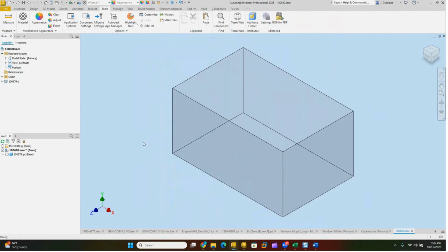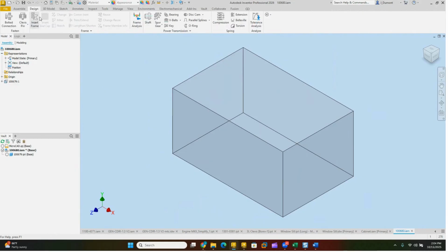names, because if you do the bolted connection, the first time Mike used it or Scott, you're going to create bolted connection 1. You try to check it in, bolted connection 1, it doesn't work. Same thing, it's going to happen over and over. Frames is going to always use the same file name, and when you try to check it in, it's a problem. So when I'm using Inventor and I'm using Vault, and I'm doing things like the frame generator,